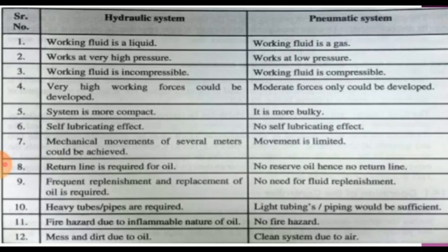So here is a comparison of hydraulic and pneumatic systems. In a hydraulic system, the working fluid is a liquid. In a pneumatic system, it is a gas. Hydraulics works at very high pressure and pneumatics works at low pressure. In a hydraulic system, the fluid is incompressible and very high working forces can be developed.